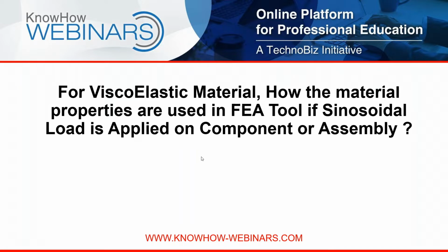One would be the hyperelastic material module, in which you input the stress strain graphs of different tests like uniaxial tension, planar shear, volumetric compression, and so on. Apart from this, you have 2 alternate inputs for viscoelastic data. You can carry out your stress relaxation and creep experiments, and there is something known as a Prony series by which you can import that data.